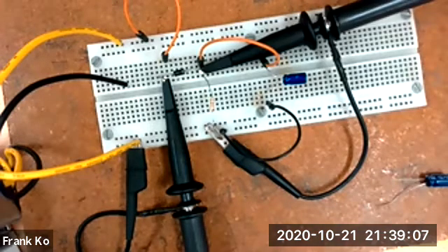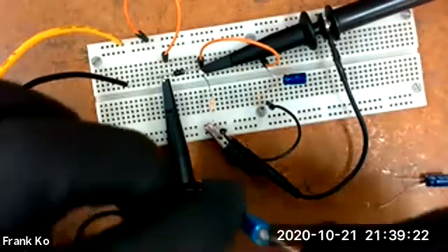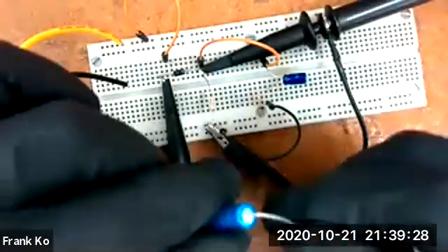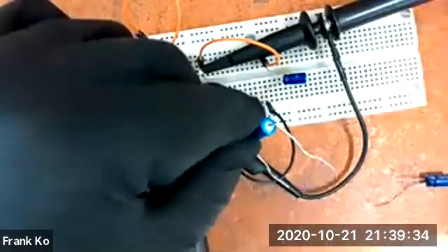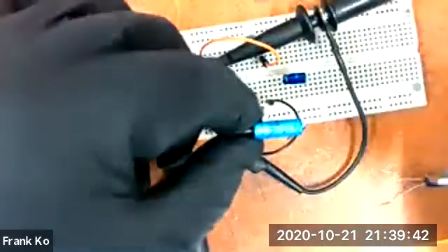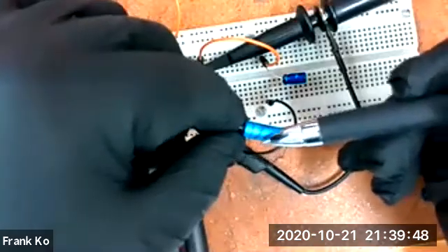Be mindful of your polarities, because you know what can happen if these are wired backwards. How can you tell which one is negative on a capacitor that is not marked? It's really easy. These are marked actually, because you should see a little plus sign on one part of the body of the capacitor. So that's your positive lead, and you should see a stripe. That's the negative side of the capacitor.